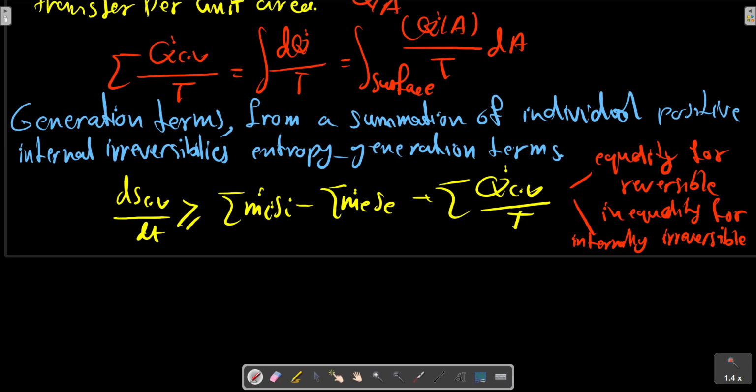The form of the second law is general such that the particular case results in a form that is a subset of the form. Examples of various classes of problems are illustrated in the following sections. If there is no mass flow into or out of the control volume, it is simplified to a control mass and the equation for the total entropy reverts back to a simpler